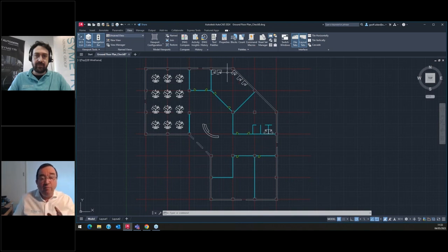Now, some people haven't used things like the drawing compare. I particularly like drawing compare. Now, two things to talk about here at the moment. This particular drawing, if I'm assuming this is my space planning little project, so I'm replacing desks and things like this in a space planning concept, this is an external reference, which is my exterior walls.